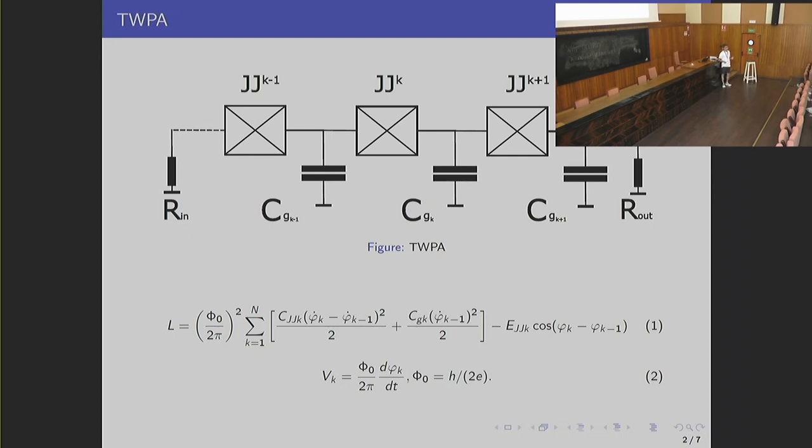Yeah, it's possible actually, but if your impedance is matched, your reflection is almost 0 in that sense. We want to make it impedance matched to decrease such reflection. But it could also be made in such a way that we make so big an impedance mismatch that our reflection could help us to obtain the gain. But it's another idea which our group used, and I didn't tell you about it here.